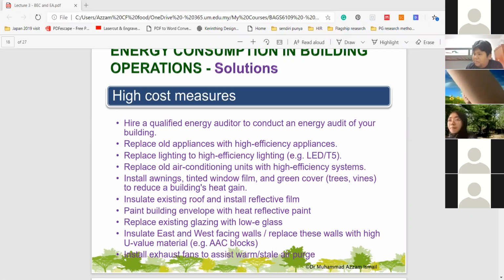Red bricks, they come in lorries, in trucks, and then they get dumped onto the ground. Okay? And then usually easily between 10 to 20% of the bricks get broken. Not good in terms of quality, building quality at the end of the day, the quality of work, the workmanship. Not as good as AAC, because AAC is nice and clean and smooth.